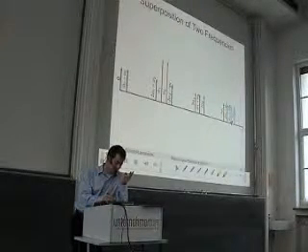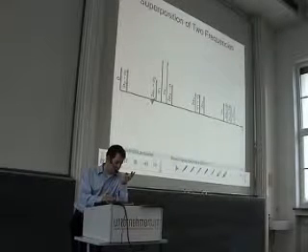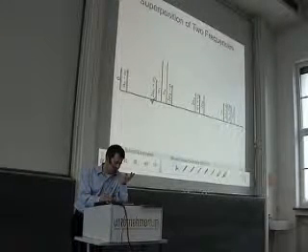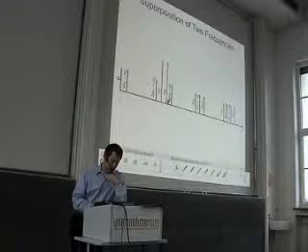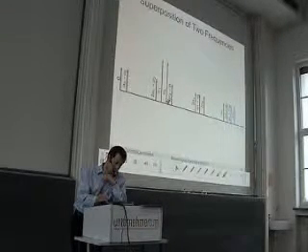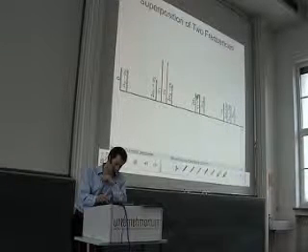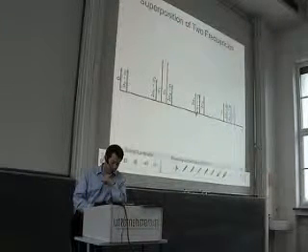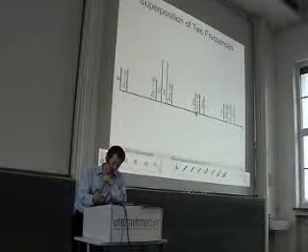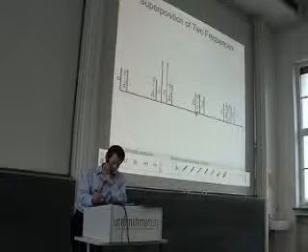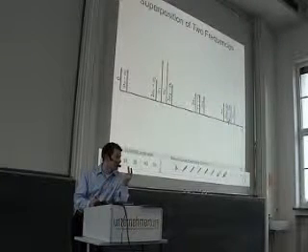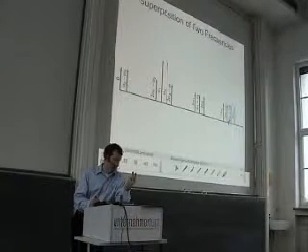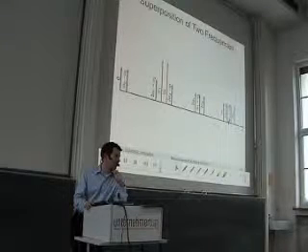We get a component which is 1 delta omega below and 1 delta omega above the 2 fundamentals. And there is also a component right in between the second harmonics, and there are components in between the third harmonics here. So we go in with 2 tones and we get all of this out.